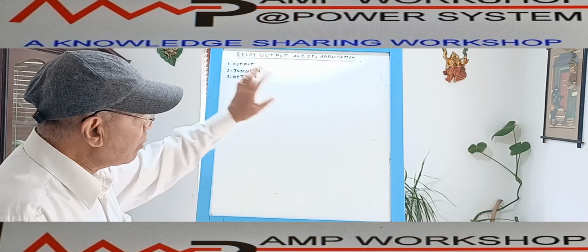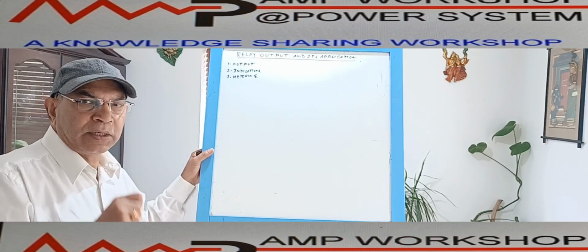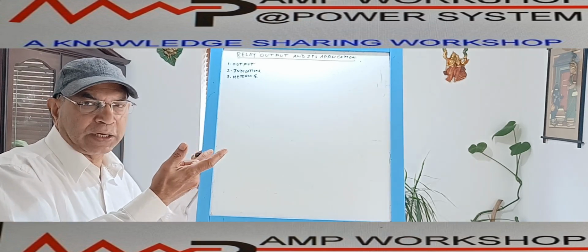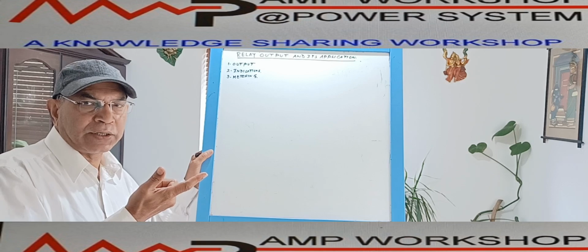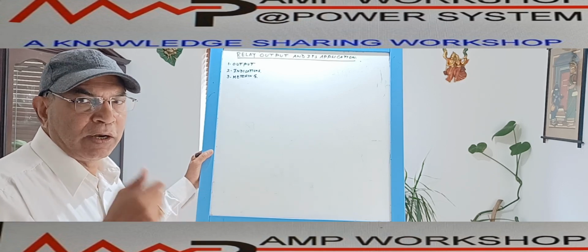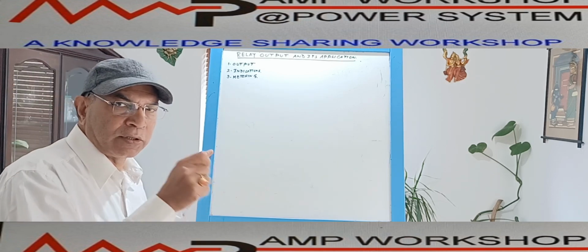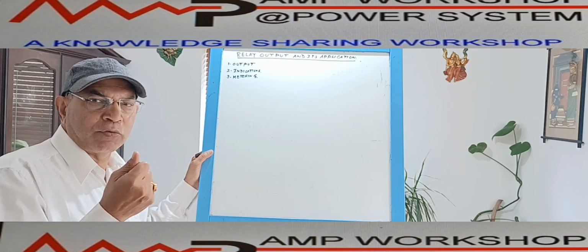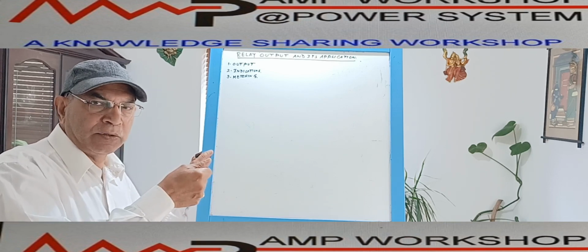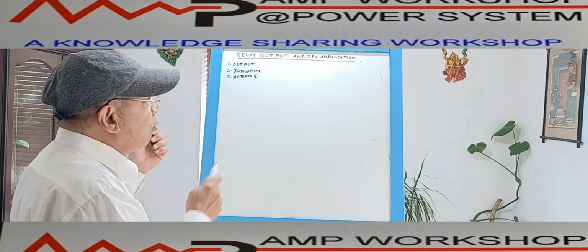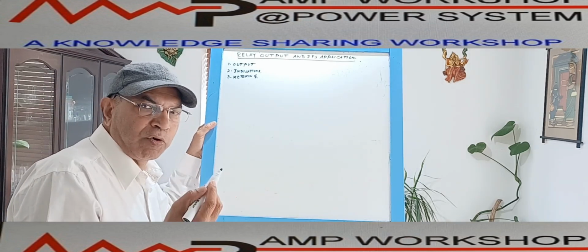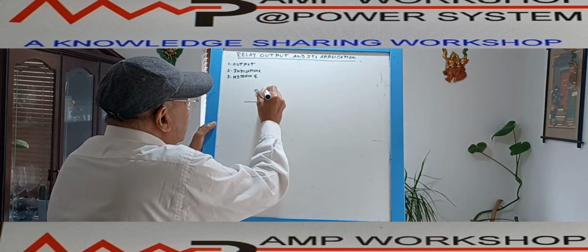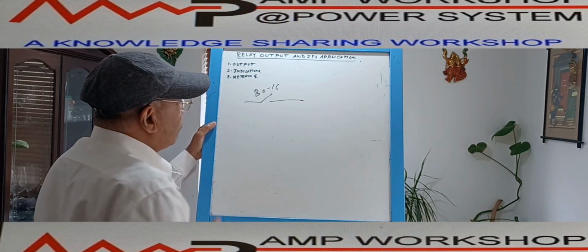Similarly, from the protection relay itself, there is a button. If we press the button, we can assign one of the output contacts, and that output contact will activate. When we press that particular closing button on the relay itself, there is a close and open button, breaker close, breaker open. If I press that close button, it will activate one of the output contacts, and we can assign which one. Suppose we want to assign output contact B016 for the closing circuit.